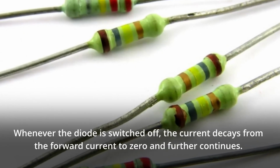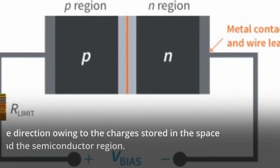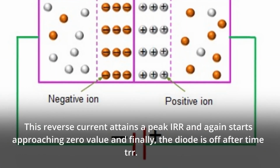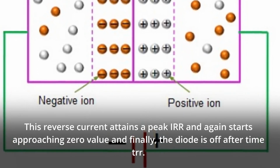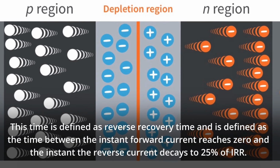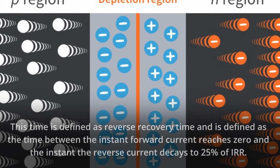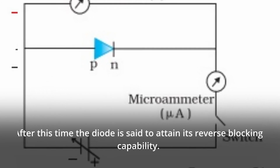Whenever the diode is switched off, the current decays from the forward current to zero and further continues in the reverse direction owing to the charges stored in the space charge region and the semiconductor region. This reverse current attains a peak IRR and again starts approaching zero value, and finally, the diode is off after time TRR. This time is defined as reverse recovery time and is defined as the time between the instant forward current reaches zero and the instant the reverse current decays to 25% of IRR. After this time, the diode is said to attain its reverse blocking capability.